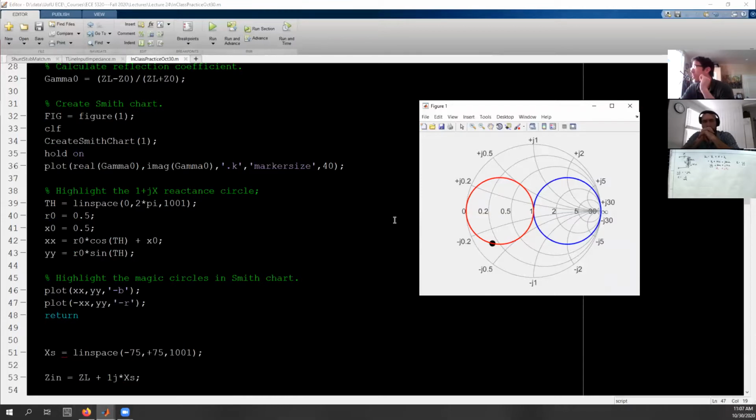This is the interesting thing about Smith charts that the book did not emphasize, and that is anything you can do in the impedance perspective, you can also do with admittance. All you have to do is flip-flop your axes here, your coordinates. So that same circle, where it was a real part of 1 for my impedance, everything will behave the same. It's just on the left side of the Smith chart.